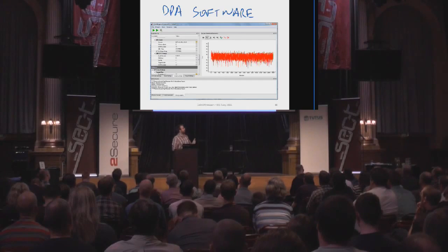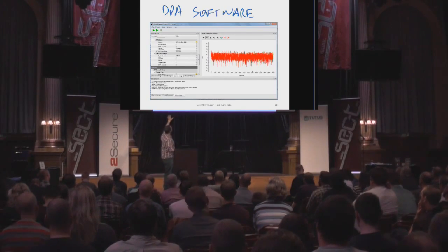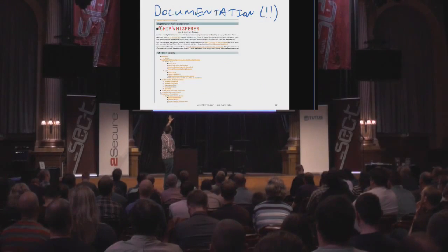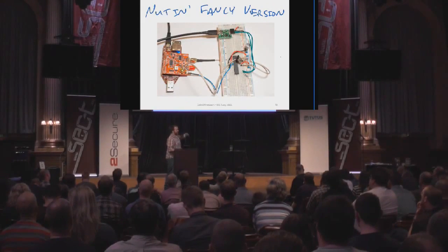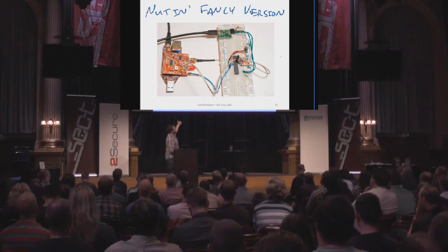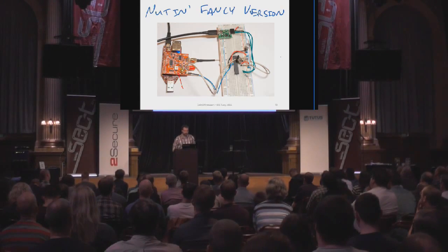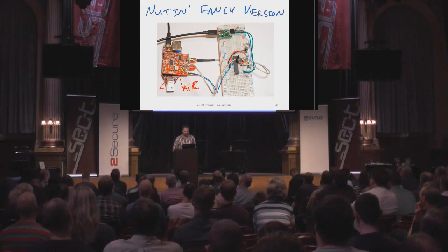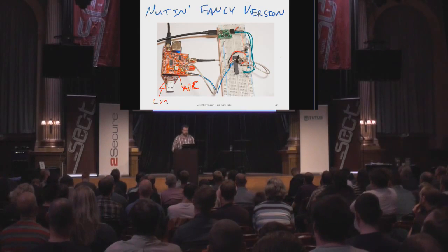The software I've already showed you. The interesting thing with the software, so this was the capture and the analyzer, is that you don't necessarily need to use it with just this hardware. There's other FPGA boards you can interface to if you want to do the capture. So this is using an ADC board here with an AVNet LX9 board here.